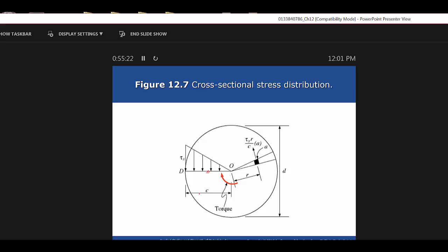Okay. Note too that this is the maximum torque without exceeding the ultimate shear strength, or allowable shear stress, and that would be the upper limit. In other words, you couldn't put any more on it than that based on what type of material you picked and so on. So that's what you're looking for there.